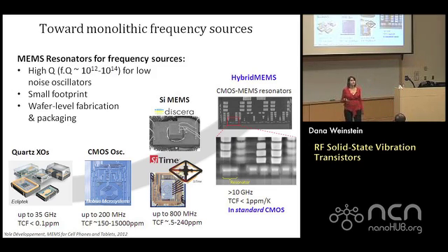And so the quality factors of these frequency sources are typically much worse, orders of magnitude worse than mechanical crystals. In addition to that, it's just metals, right? And the thermal expansion coefficient and temperature coefficient of resistance and so forth cause a major problem. And the temperature coefficient of frequency of these frequency sources is in no way comparable to what you can get with these crystals. So really, we want to leverage the best of both of these worlds. We want CMOS integration, but we want the high performance that quartz crystals can give you.